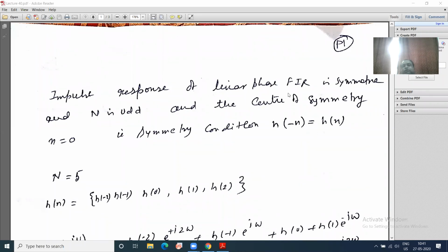Before that, today we will discuss a few more things which I am left with. So last class we have discussed FIR system and IIR system, with symmetric and anti-symmetric filter response. Then we have discussed symmetry about (N-1)/2, where N is the number of samples to be considered for filter design. In other words, they are the filter coefficients, right? Filter coefficients in time domain, right?